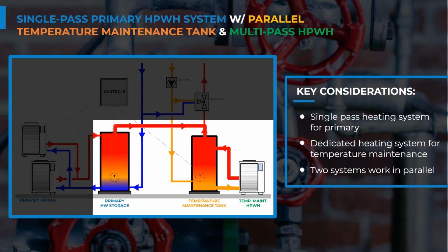If we were to take this water to the bottom of this tank, like we do in our swing tank design, then we risk having the heat pump try to heat up really hot water, because this will typically be coming out at maybe 130 to 140 degrees. So if we took that in there, then our heat pump will get 130 to 140 degrees and try to put heat into it. But that's going to be a very challenging operational point and will probably result in a pressure issue and an error alarm in that heat pump. So it's important to have this parallel connection.